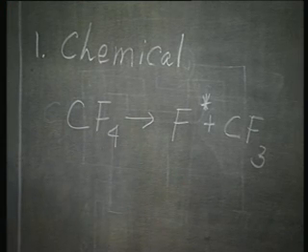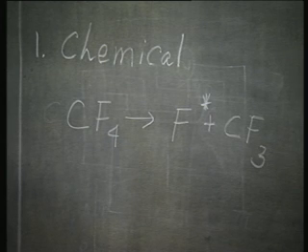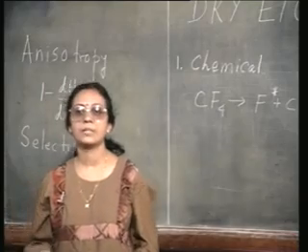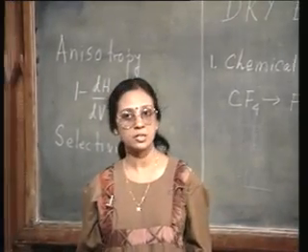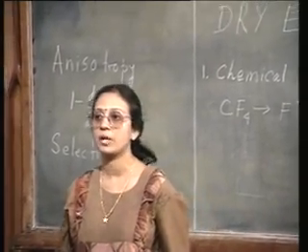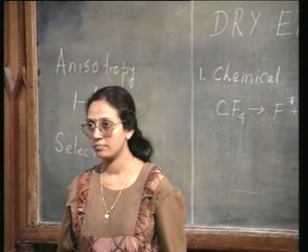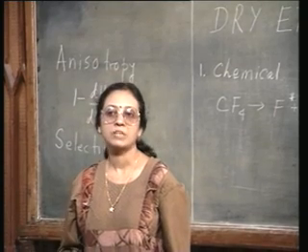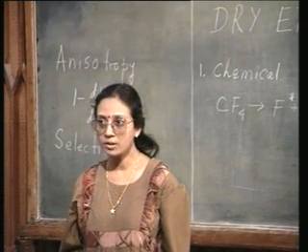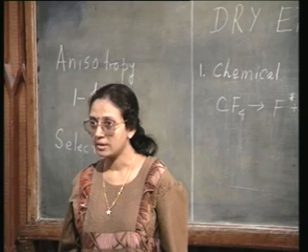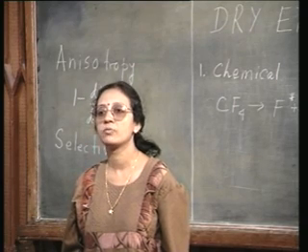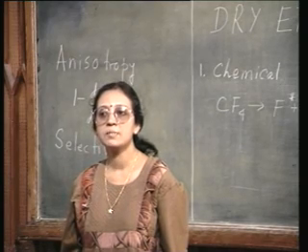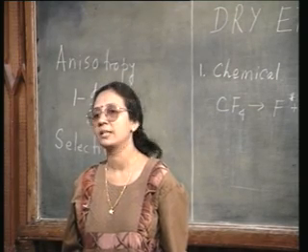Normally, it is not possible unless you provide enormous amount of energy. Here that energy is being supplied by the hot electrons in plasma, these electrons which have acquired very high energy. Okay. So, the etching is chemical, no ions are involved in this, it is simply silicon reacting with fluorine. The role of plasma is, as I said, limited to generating the active fluorine species.